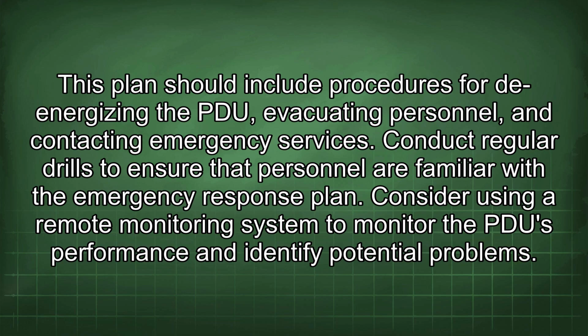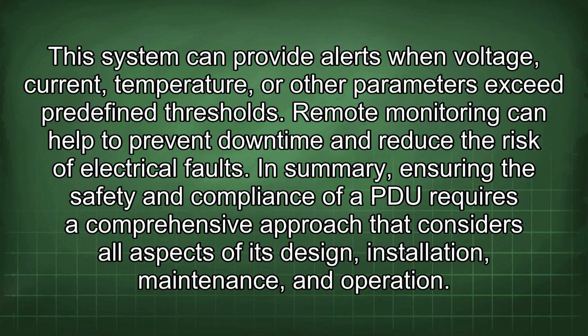Consider using a remote monitoring system to monitor the PDU performance and identify potential problems. This system can provide alerts when voltage, current, temperature, or other parameters exceed predefined thresholds. Remote monitoring can help to prevent downtime and reduce the risk of electrical faults.